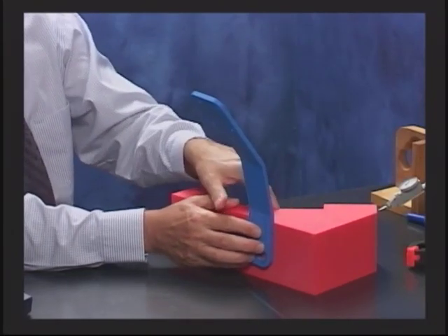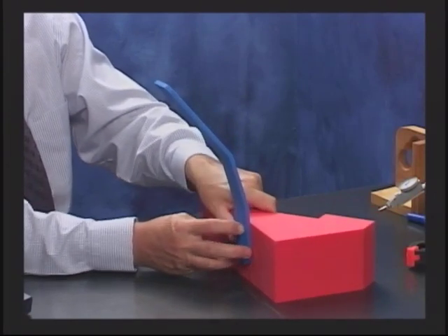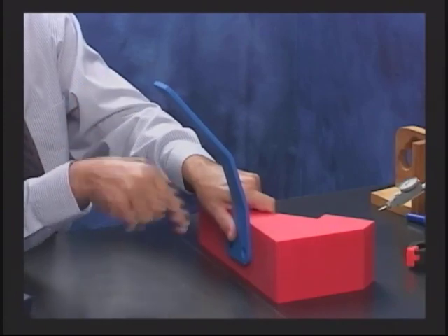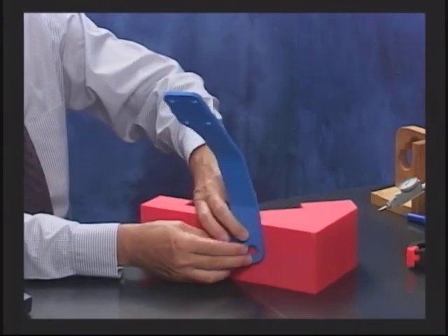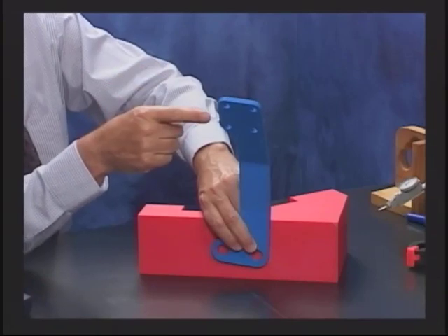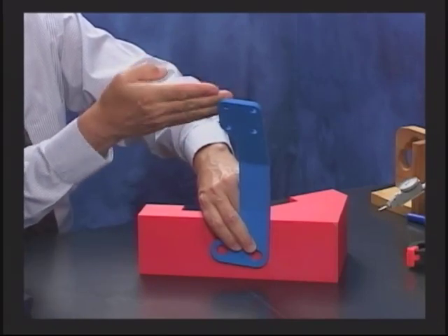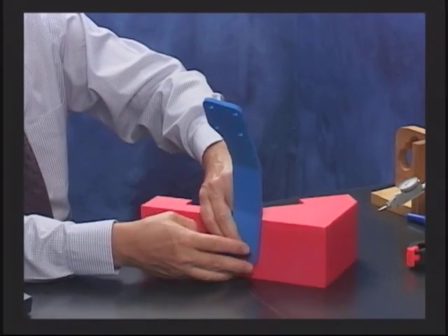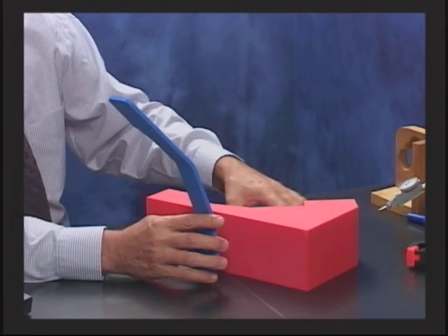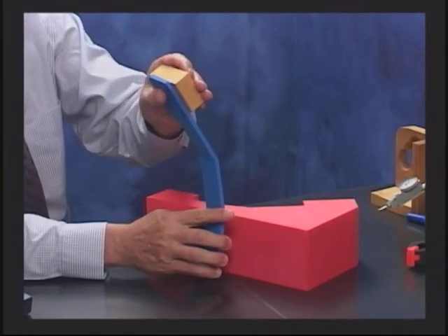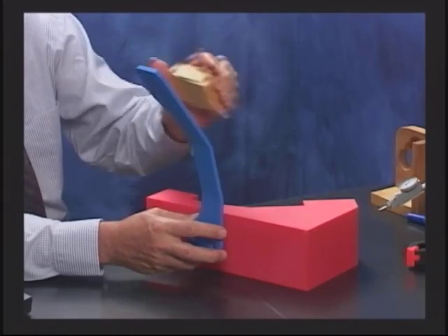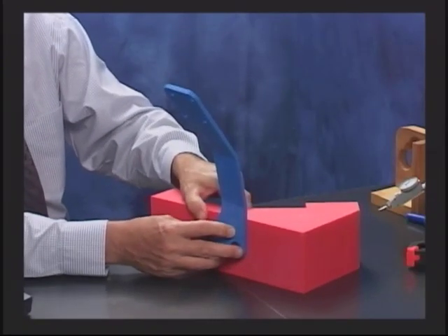So the way that I thought of looking at it is that I said, okay, what's the leader is, this is the datum, it mounts up against that face, and this is the one that's going to be off. So if I'm imagining I'm standing on a truck, it's mounted up, and I point to that surface, and I say that surface can move within 4 millimeters, that's how much the fuel cooler is moving around on that surface. Now, of course, if you're the fuel cooler designer, you probably think that this is the fuel cooler, that's 0, and then the frame moves to your fuel cooler, but that's probably not the way that it works. So that's why I selected the face as the datum.